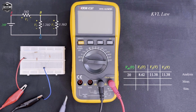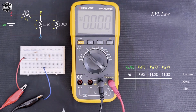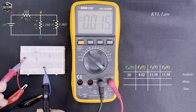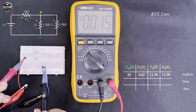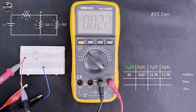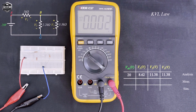Let's first measure the battery to be sure of its exact value. Here I measure between node A and G, meaning the battery value. I'll connect the battery. Yes, the battery voltage. So with DC, our battery value is 20 volts.